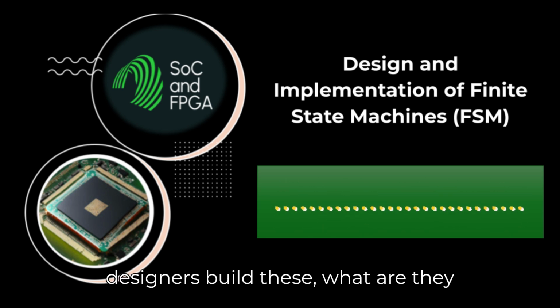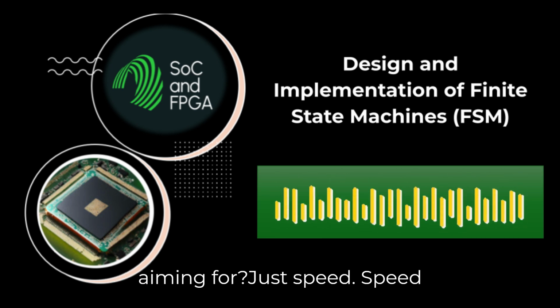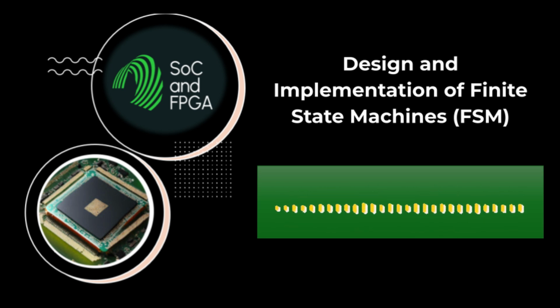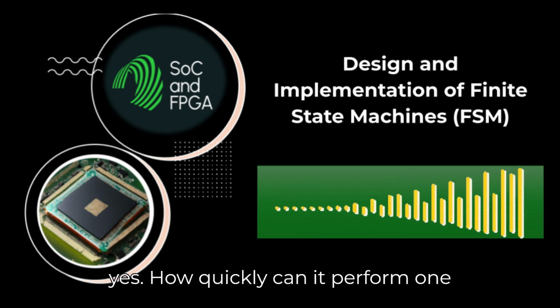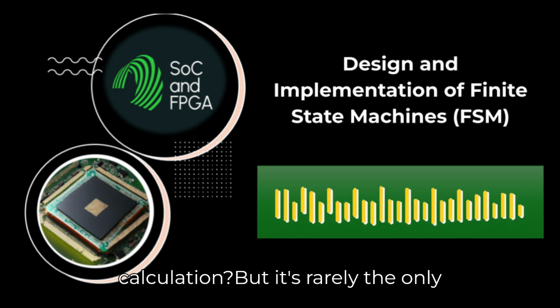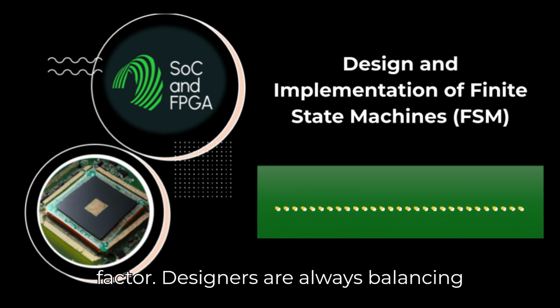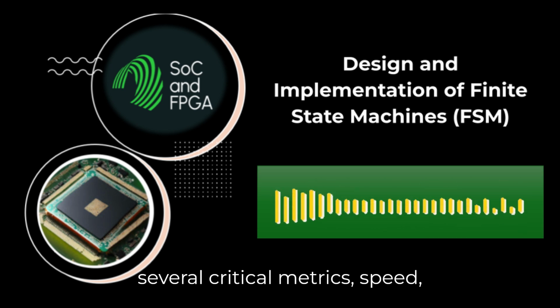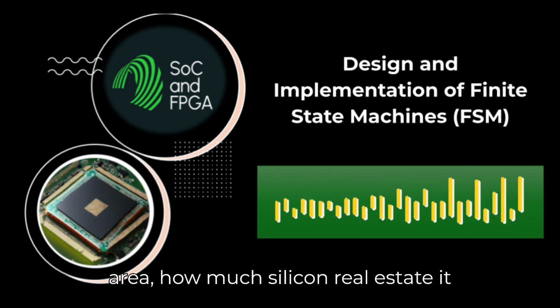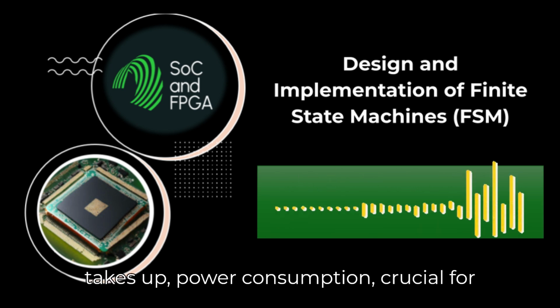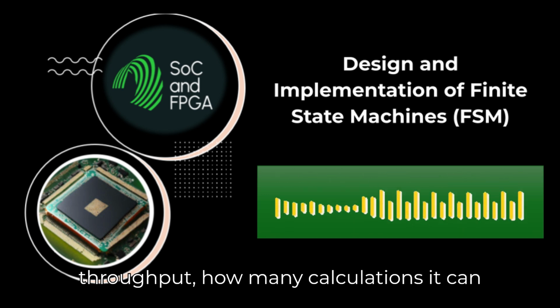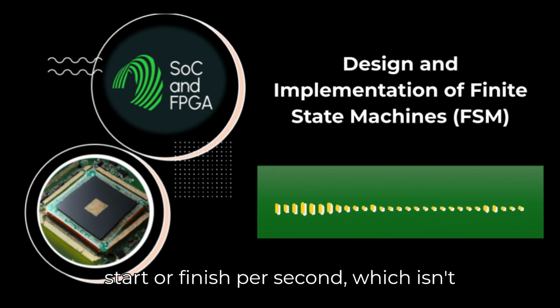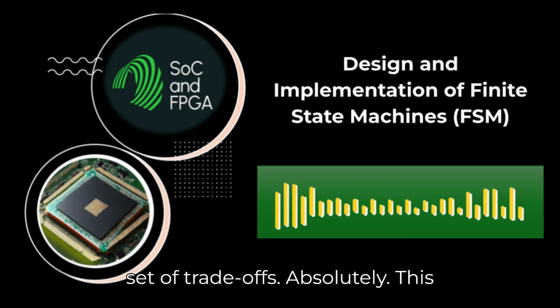When designers build these, what are they aiming for? Just speed? Speed or low latency is usually very important, yes. How quickly can it perform one calculation? But it's rarely the only factor. Designers are always balancing several critical metrics: speed, area, how much silicon real estate it takes up, power consumption, crucial for battery life and heat, and sometimes throughput, how many calculations it can start or finish per second, which isn't always the same as latency. So another set of trade-offs.